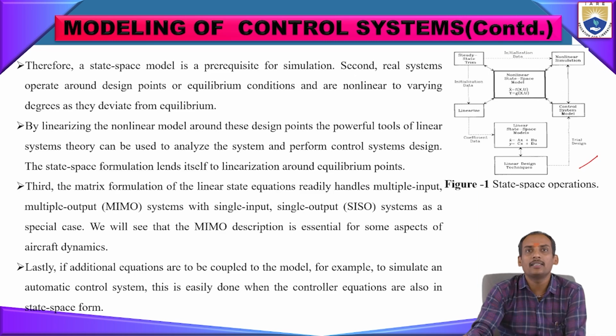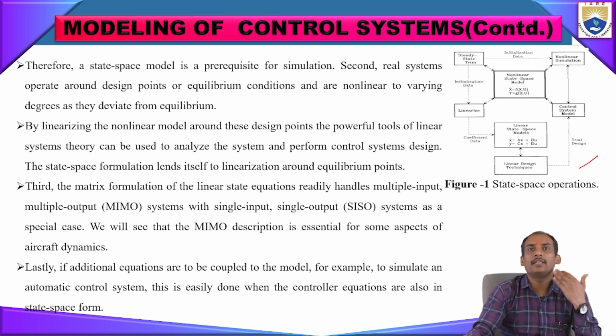So by the linearization of this entire system, the new linear model around these design points may be a powerful tool of linear systems theory, and that can be used to analyze system performance and system design.